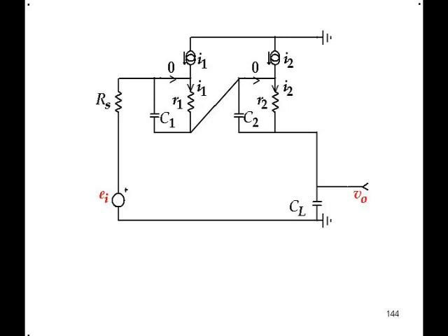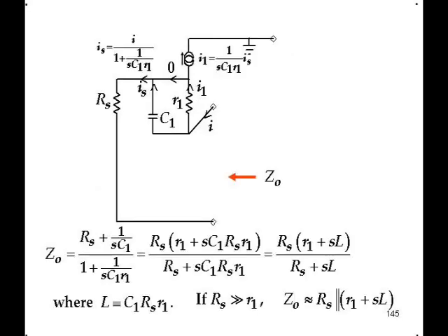That's the basic model. Now, it's worthwhile before we start doing any analysis to figure out why you have a potential instability in the first place. So I stripped this down to the essential features. We've got a load capacitance CL. Why is that model potentially unstable? Well, one way to look at it is consider the first stage only. Do a little analysis on it to find its output impedance, ZO. Doesn't take much algebra. Don't have to go through the steps right here.